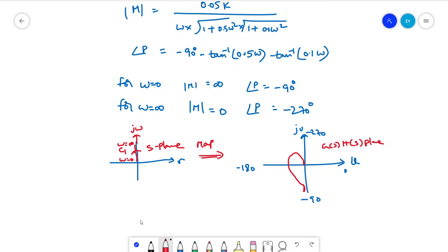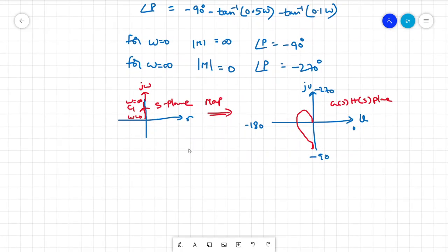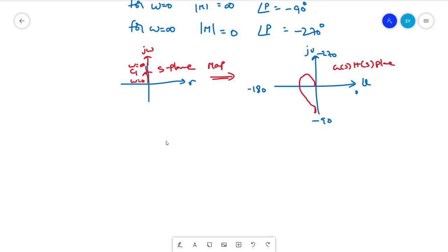So what is C2? Now C2 will be from infinity to minus infinity. In yesterday's class we discussed some conditions. If you are having the plot on the right half of the S plane, and it is going from minus infinity to infinity, making the radius infinity, what are the conditions we discussed? The S term will tend to infinity, r into e power j theta, right? So consider case 2, for C2.